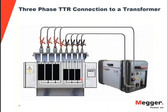Because of such low numbers, we run into these questions from a tech support point of view, where they are testing small dry type transformers or small pad mount transformers, oil filled pad mount transformers, and they cannot pass the 2% criteria between the phases or 5% from the factory. In those cases, it's not that your transformer is bad or anything, it's just that 2% is too low a resolution for any test instrument to give you that kind of accuracy.